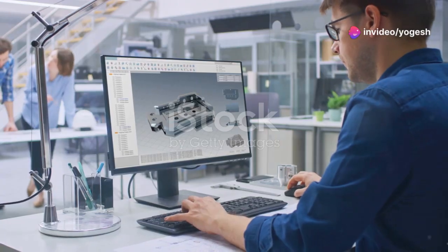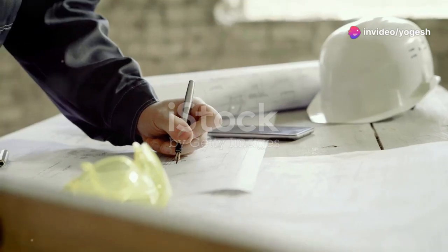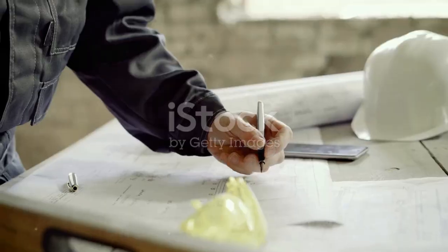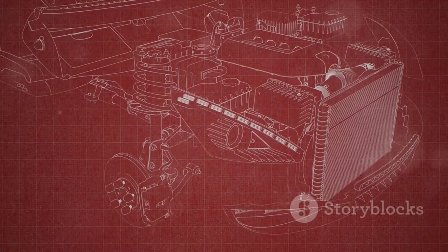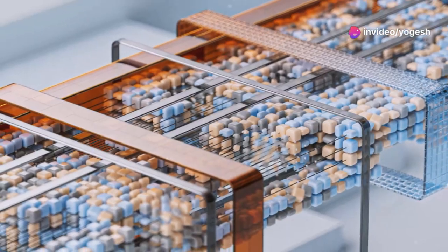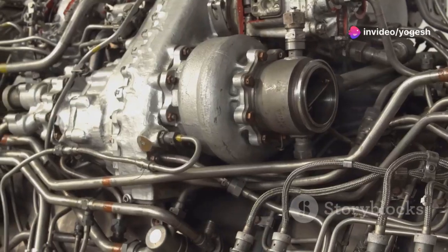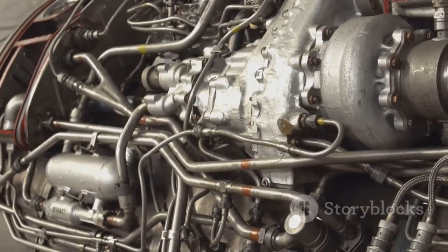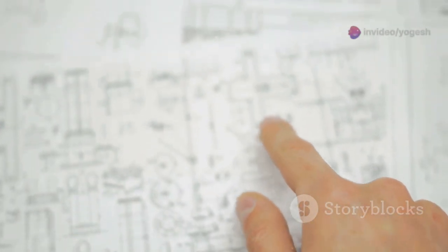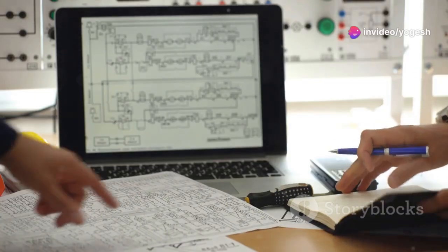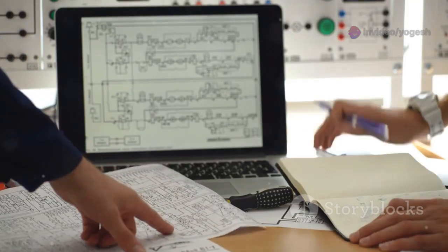Clarity is key when creating assembly drawings. Start with a logical assembly plan and use a consistent balloon numbering system. Keep views uncluttered. Break complex assemblies into sub-assemblies if needed. Use a mix of view types, isometric, exploded, sectional, and detail views to clarify each step. Add notes and tables for information that can't be shown visually, like torque specs or inspection points. Always have someone unfamiliar with the design review the drawing for clarity.